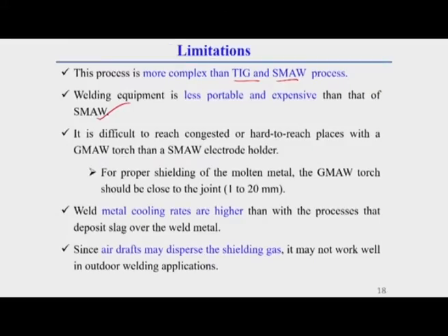That is why, for hard-to-reach positions or congested areas where the gun is difficult to reach, this type of welding is not preferable. The SMAW welding process is more suitable there, because only a stick has to be put in place. So there, stick welding is more preferable.